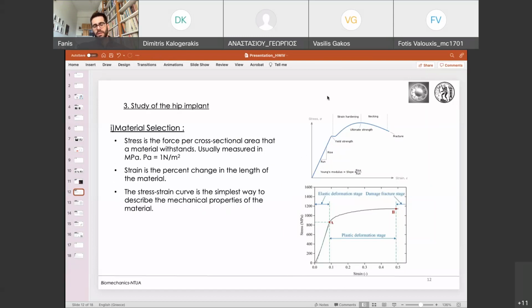So this is not a so typical stress and strain curve, but you can see a lot of things on it. This first region that is linear, it's the elastic region. The slope of this line essentially is the Young modulus or elastic modulus. When you reach the end of the elastic region and go into the plastic deformation, you have the yield strength. And moving on, you have the ultimate strength, which is the biggest stress a material can withstand, and you have the fracture. Now bear in mind, because this is not for a specific material, it's kind of a weird diagram.